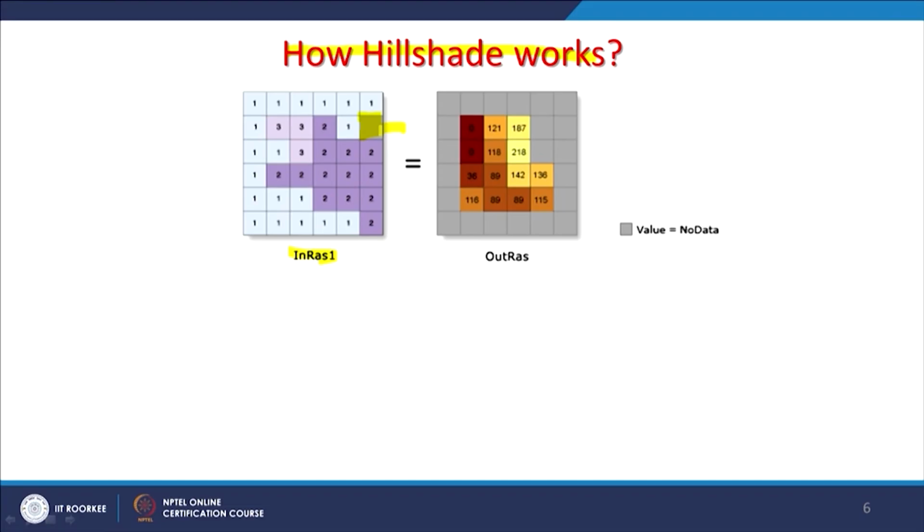Further, output will also not have any data along the boundary, a one cell thick boundary all along your output. So, only for the center area, excluding that boundary, will you have values. And as you remember, 7 cells out of 8 cells should have a value. For the center cell calculation, because otherwise there are 9 cells, we are looking at the 8 neighbors.